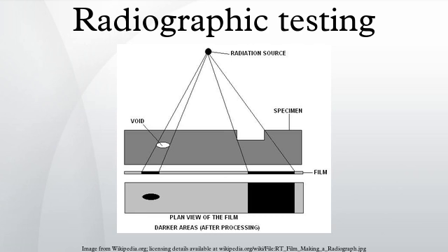This is very important, as most construction standards permit some level of defect acceptance, depending on the type and size of the defect. To the trained radiographer, subtle variations in visible film density provide the technician the ability to not only accurately locate a defect, but identify its type, size and location. It is an interpretation that can be physically reviewed and confirmed by others, possibly eliminating the need for expensive and unnecessary repairs.